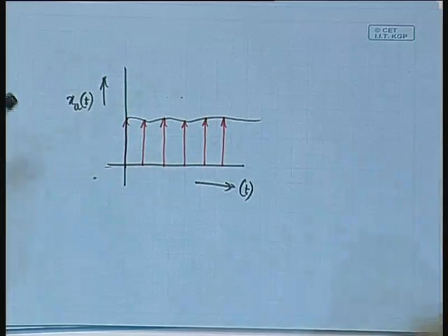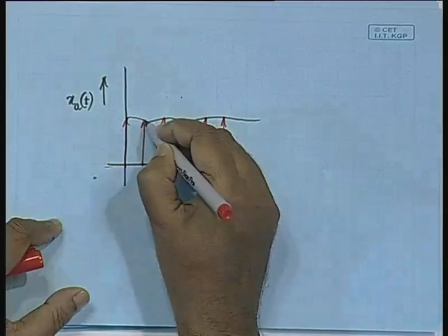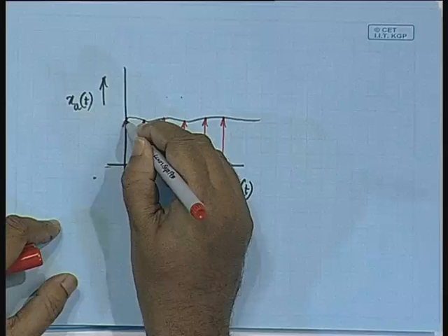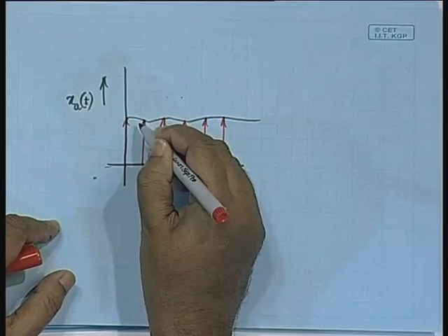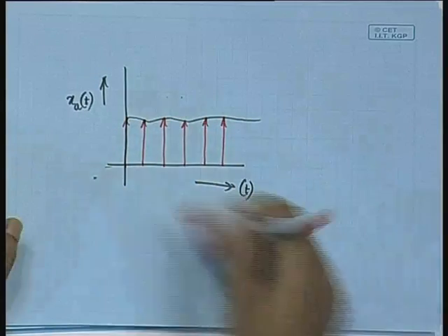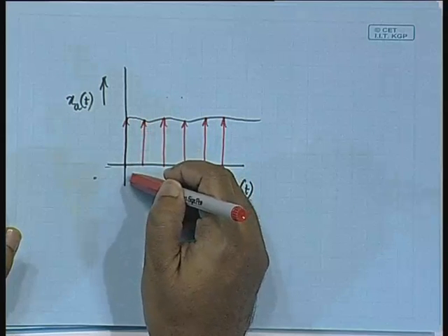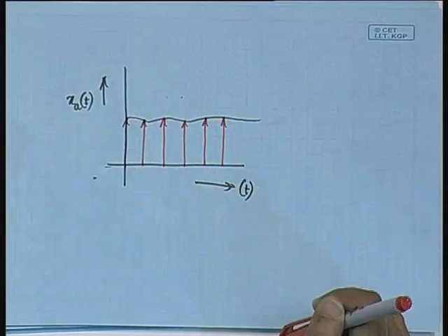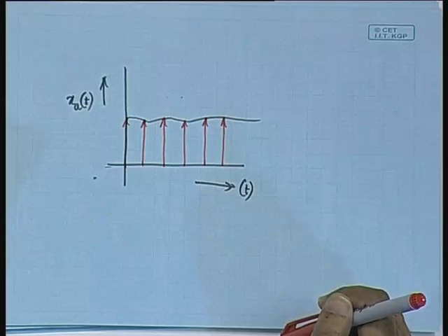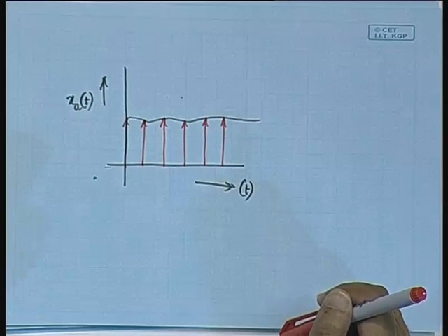Now, when the second sample comes, we are going to predict the second sample based on the first one. Clearly the first sample is slightly higher than the second sample. So, we can say that x tilde of n will be slightly higher as compared to x of n, and slightly higher means that immediately we can conclude that d of n is going to be negative.